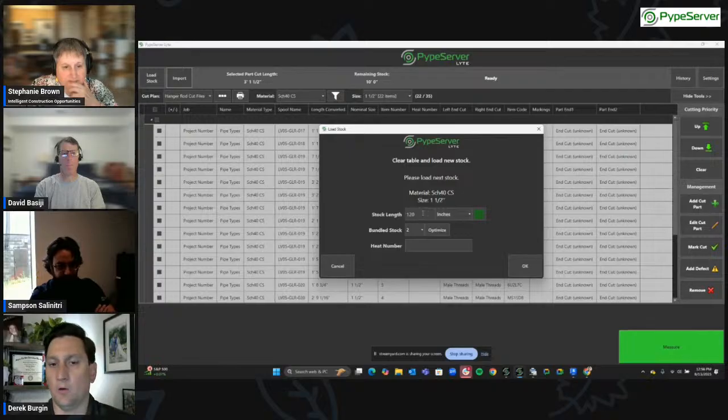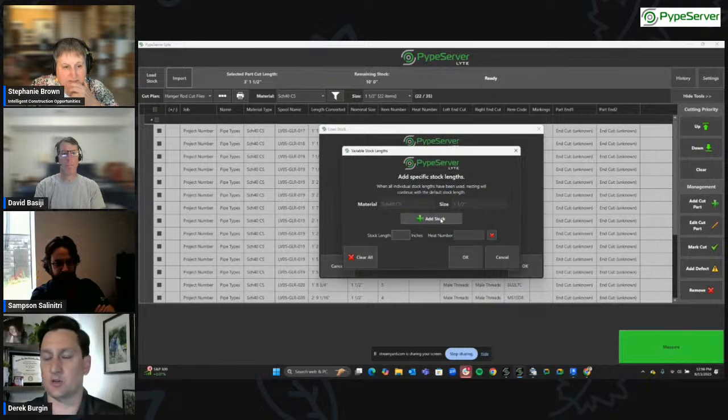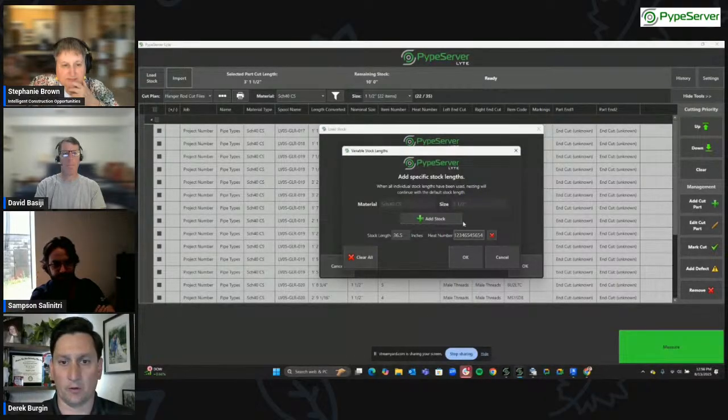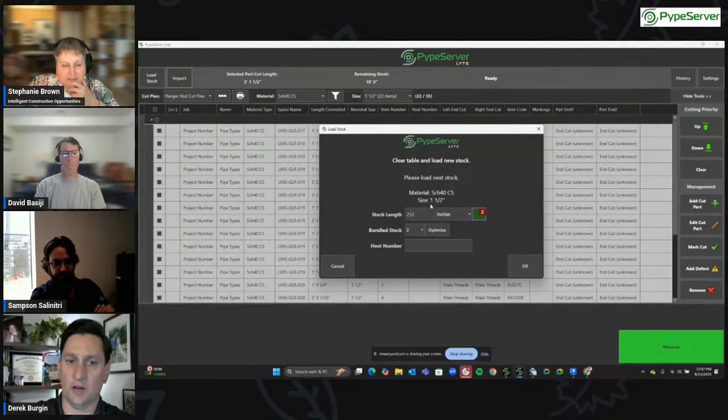It's going to say, what length of pipe are we currently working with? Well, we can put 252 as our single random. That would be our standard. But say, for instance, our shop has a scrap pile. Those scrap piles can be ever growing, but let's put them to work here. We have the ability to say, hey, we have a piece that's 36.5 inches, and if you're doing heat number tracking, we can throw that number in right there. Then we could say, hey, we have another piece that's 96 inches and it has this heat number to it. And then after that, it's going to go to our standard stock length of 252.